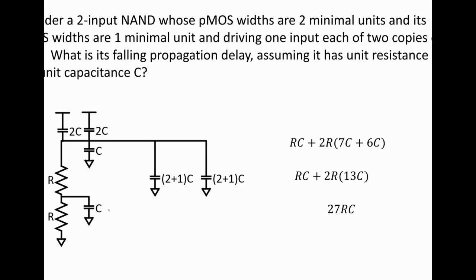Yes, that's a good point, except that typically the way these are designed is that they would share 1 diffusion area. I should have made that point, I should have clarified that last lecture. They would be sharing a diffusion area. Transistors that are in both series and parallel can share diffusion areas. So there's not necessarily 2 separate diffusion areas. They're merged into 1.